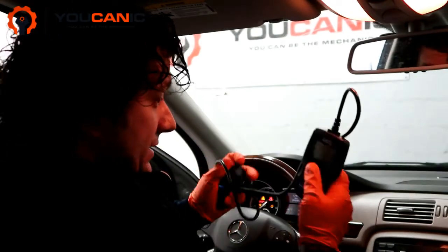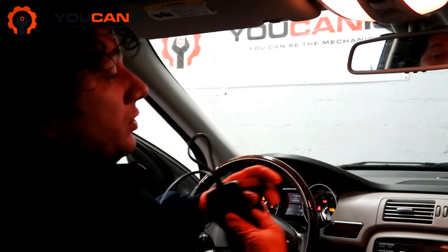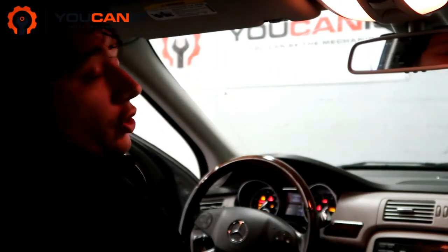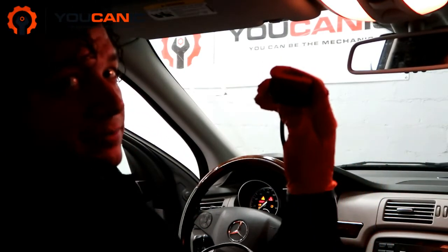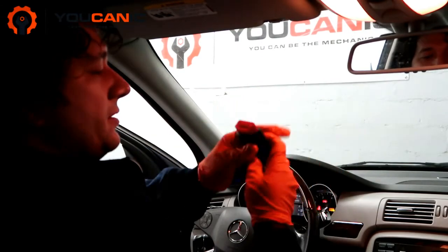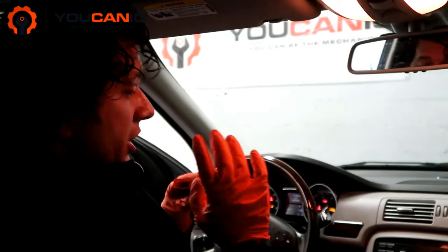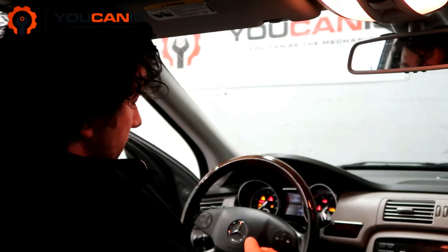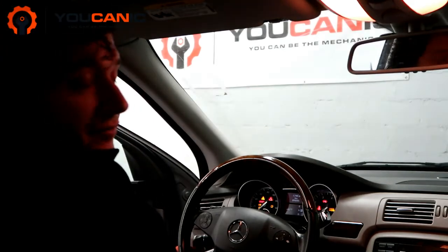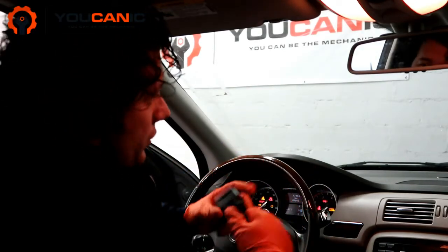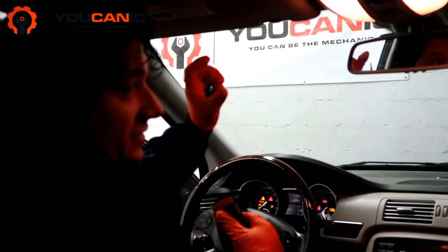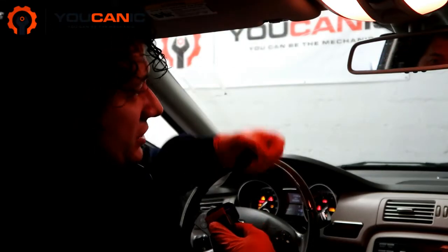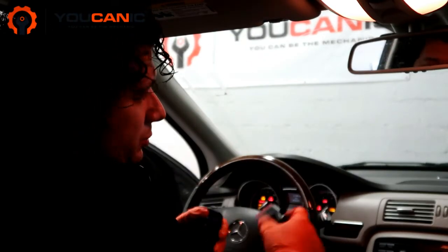We're going to connect this to the OBD2 port. All vehicles have the OBD2 port. It's called the onboard diagnostic port, and it's located under the dashboard. It has a trapezoid shape, so this is the male and the female is under the dash. Most cars will have it right under the dash. It might be covered, or it might be at the fuse panel, where you pop off a cover and then you'll see the port. BMWs and Mercedes have it further down, still with a little cover about that big. You just pop that out and then you'll see the port.